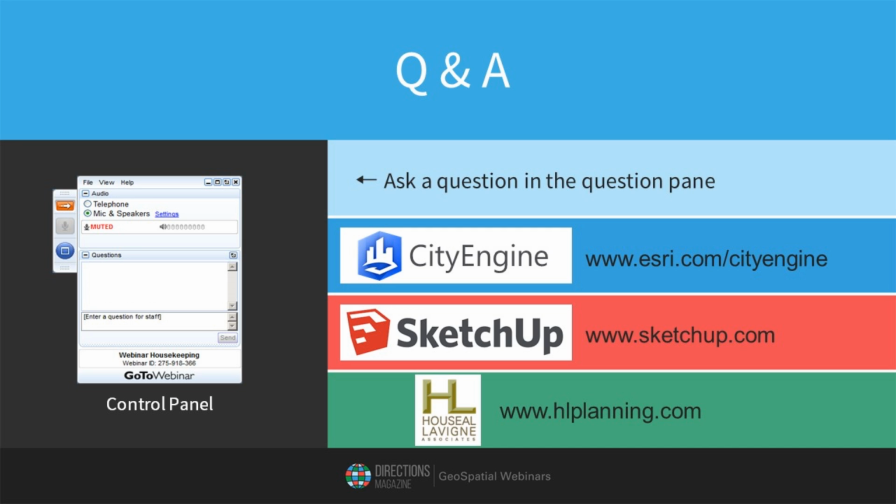Chris, you covered it for SketchUp pretty well, and it's exactly the same as what Chris had up on the screen for SketchUp, in that you're able to pull in CAD, Collada, OBJ, FBX, geodatabase, shapefiles, etc. And the nice thing about CityEngine, as well as SketchUp, is the ability to export to those same exact formats that you can import. So interoperability is key in 3D software in general, and we focus on providing the best, most up-to-date formats. So our FBX format, for instance, is up-to-date, so you can pull in your CAD as easily as you might think.